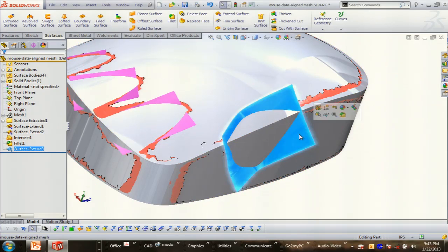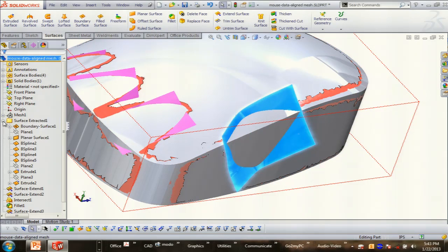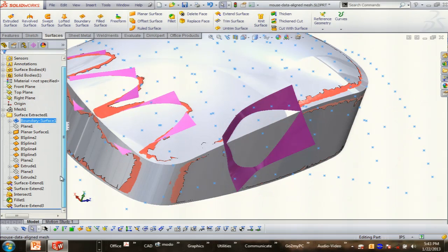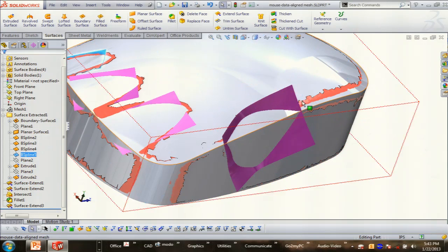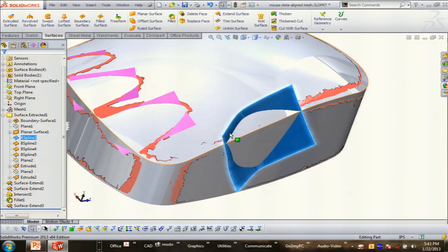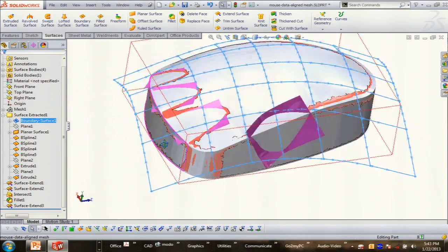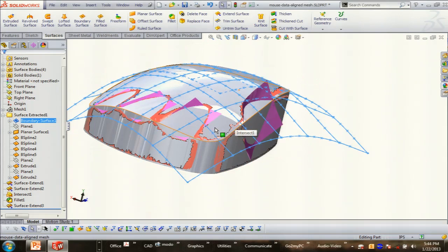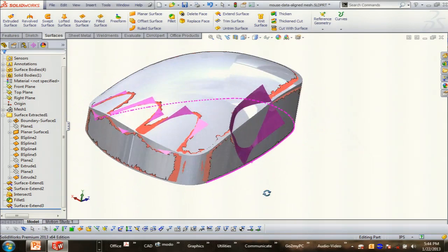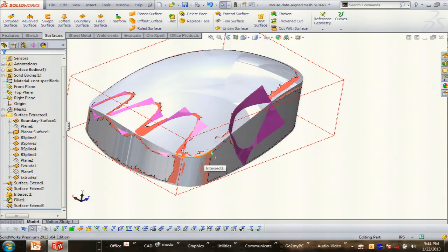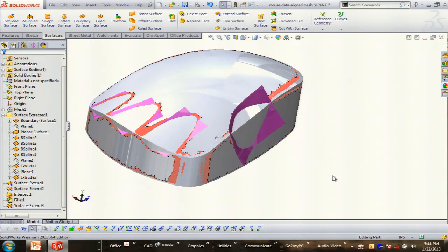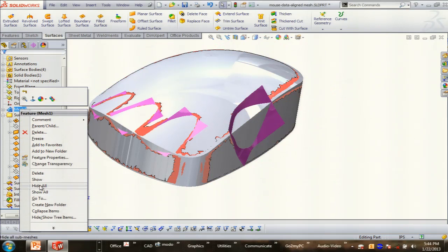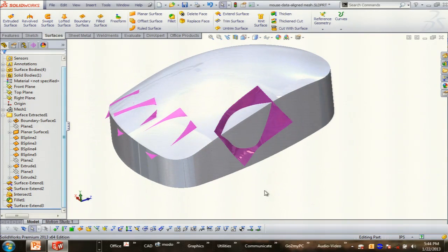But what is instructive, what you need to know, is you look at here. This thing is actually a boundary surface, if I can find it. See if I can highlight it. Okay, this is still a B-spline, yeah. But that top one, for instance, right here, that's now a SolidWorks parametric feature. So I can go back in there and continue to fit it more nicely to my mesh. And that's really helpful. So the idea here is then, all I have left to do is to create my fillets. This is a solid model now. I can hide my mesh. And that's basically what that's all about.